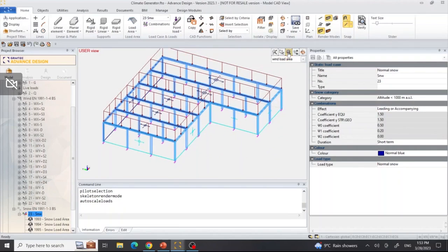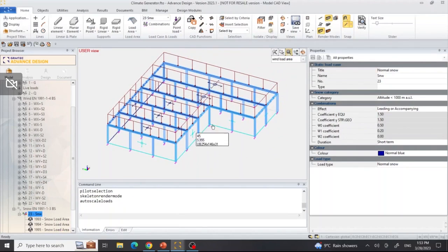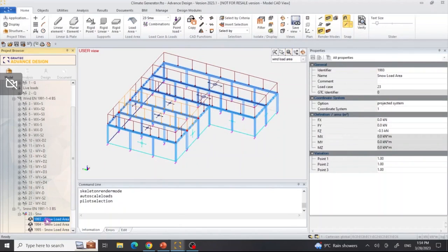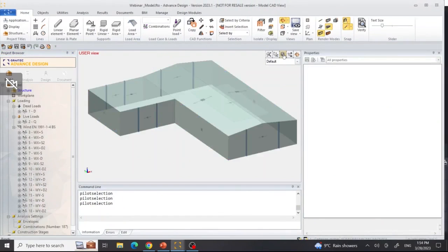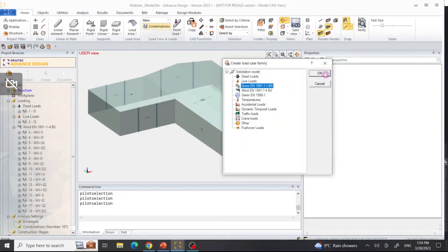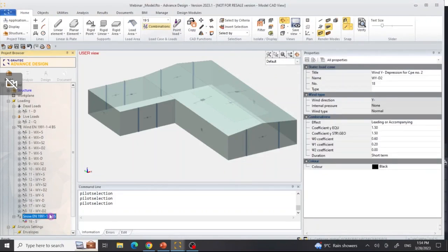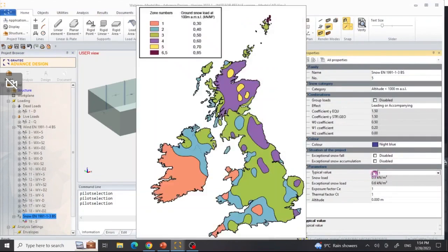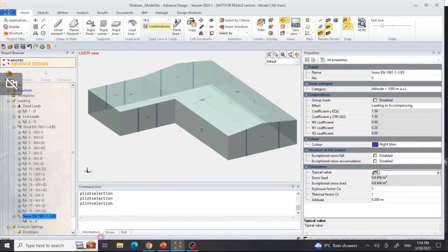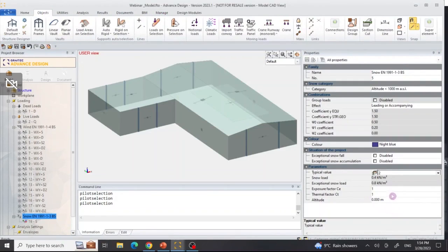And as you can see here, this is the snow load on this flat roof. By clicking here, you will see the value is -0.5. Also check this type of structure we checked earlier, the one with the 2-pitch roof. I can run the snow generator again. I am going to select again an area here around Southampton and run the calculator again. The altitude now is 0.